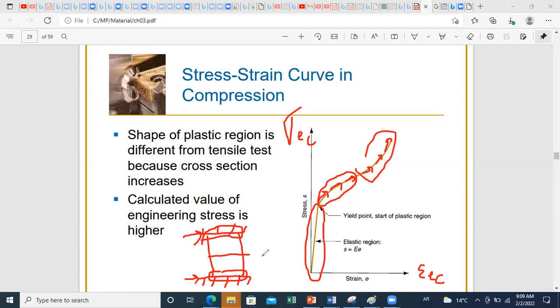Okay, and as you proceed with the test, these forces will increase, and at a certain stage they will become very large, so that they will lead to the need for higher forces and at a higher rate to continue the compression test. Okay, so in this case, additional energy will be consumed by this friction during the test. This will result in higher applied forces, which explains the increase in rate.